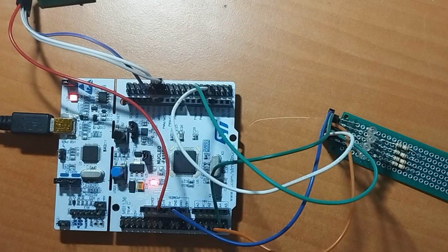To summarize, I have shown you the basics of how to add a USB MIDI interface to the STM32. Of course, the implementation of USB MIDI devices is quite complex. Using descriptors, you can add various options, such as the number of logical cables, assign string names to them, and much more. That's all about MIDI, I think.